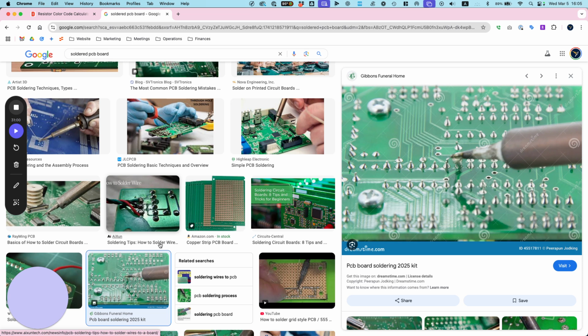I don't really see it too often, but if you have a bigger battery pack, you'll sometimes see a P. So you see a 4S2P. The P is going to be parallel. So you have 2 parallel packs of 4S. What is the voltage going to be on that one? Let me draw this again. We have another set right here. This is now parallel. What is the voltage going to be across this point right here? The same 14.8. So this is a 4S2P.